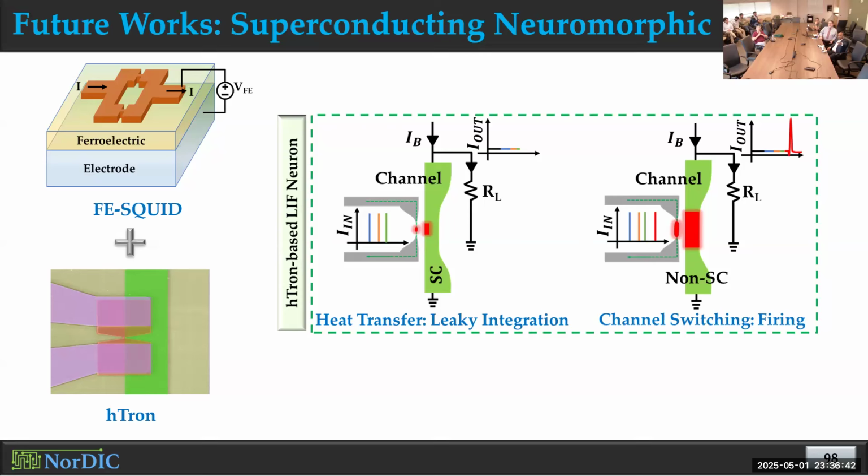So it's very cool. So basically, we're trying to use the diffusive nature of heat. If you keep providing a spike and stop, it will just diffuse away and not do anything. But if you keep doing it enough number of times, it will switch. This was all Shamiul's idea. We're just trying to leverage that. And there is a thermal reset time. So if you apply all the spikes, integration will happen. But if the thermal reset time occurs, then again you can start from the beginning. So you have that reset as well.